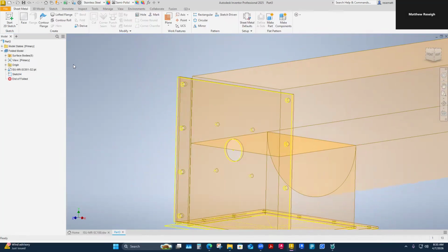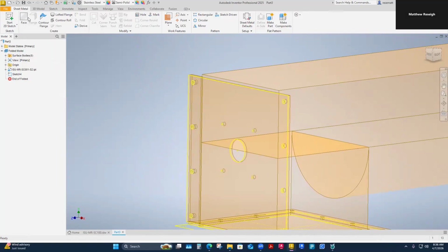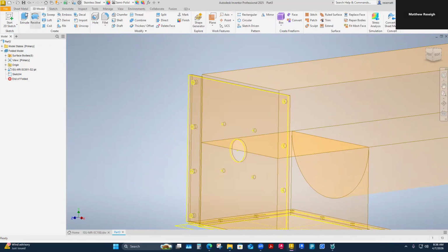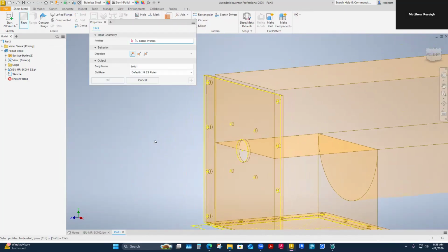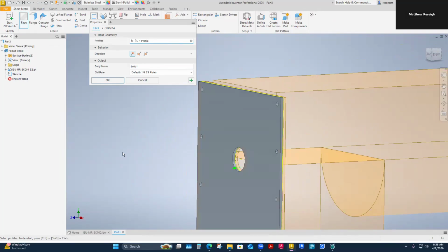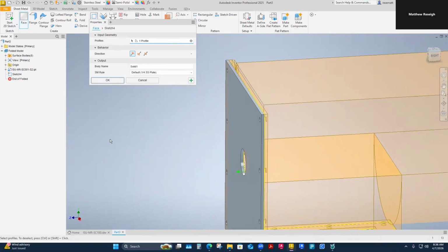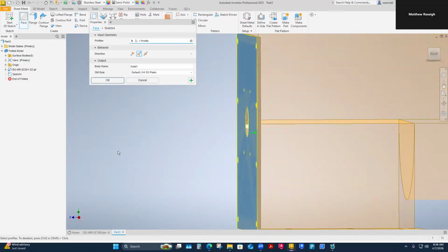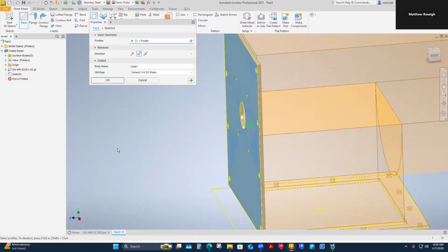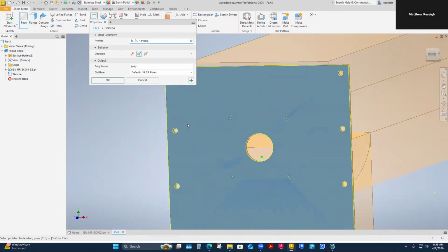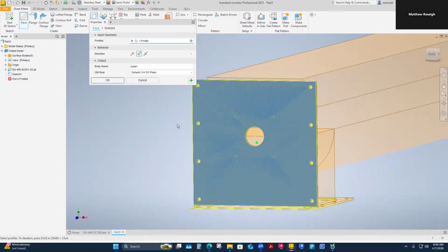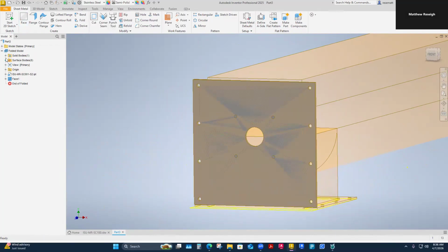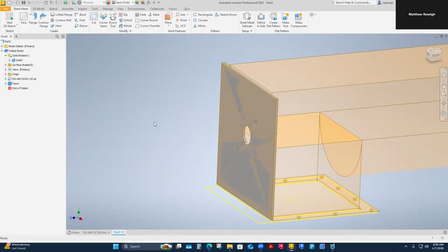So I finished that. And then I'm going to face this because we've set our sheet metal rule. Face is like extrude. You could also use extrude, but I'm going to use face. Face just needs a sketch, but it does what extrude does, only to the thickness that we've set. I want it to go this direction and lie right where the surface shows it should lie, like that. That's a new solid. It shows up. That's my first solid in my assembly.